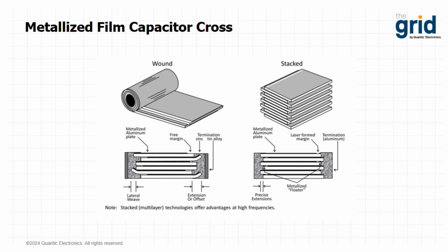That composition can create some internal stresses in the capacitor, especially during thermal cycling and self-heating. So think about when that capacitor is getting energized, thermal shock applications. Also, the manufacturing process means the winding offsets need to be rather large. For lack of better terms, there's a little bit of sloppiness involved in continuously winding capacitors.